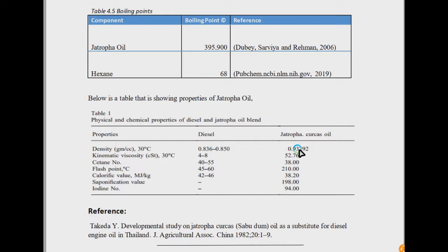From the energy balance, for each component enthalpy, from this mixture you can use an alternative of average mixture specific heat, so you can use the enthalpy. From that you can calculate the total heat that is exchanged in the extractor. Like you have heated the mixture up to 90 degrees centigrade, so the heat is exchanged between the 90 degree and the feed temperature at which the solids and the hexane enter